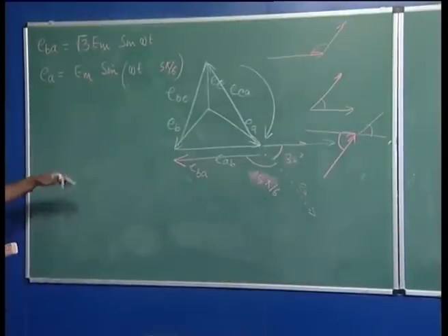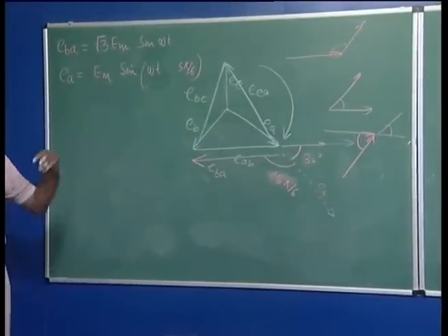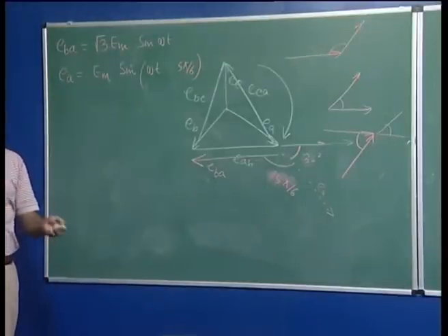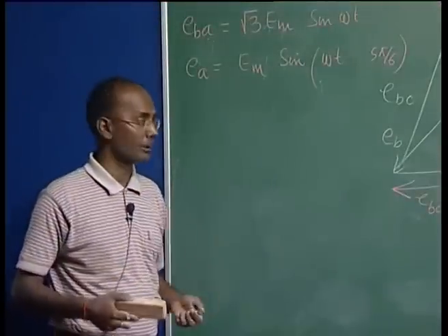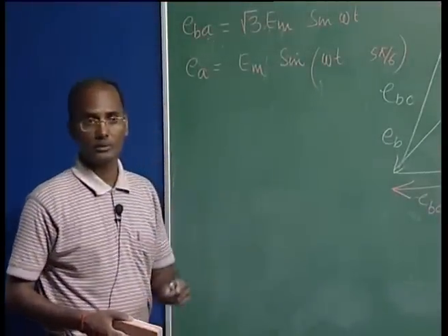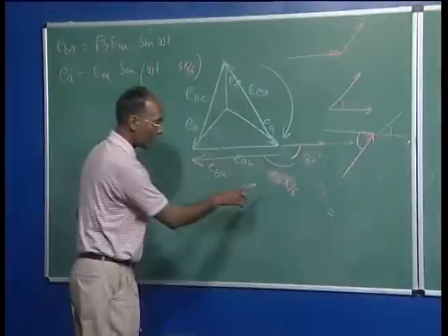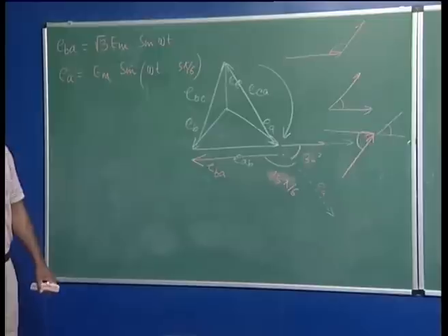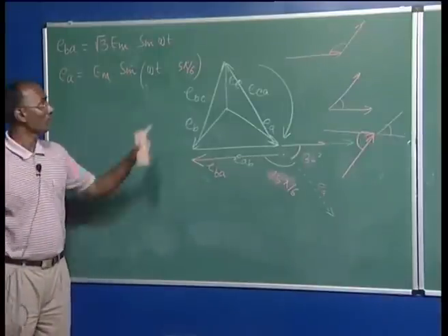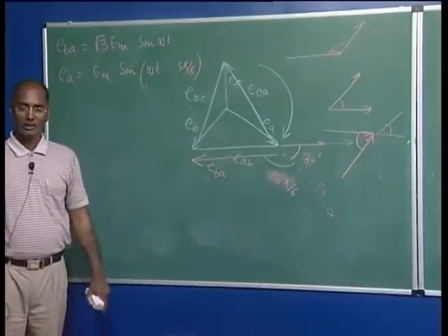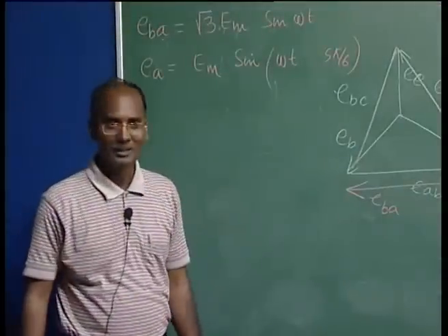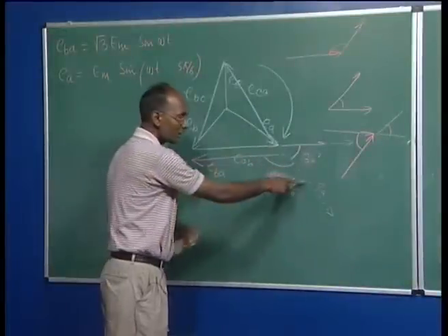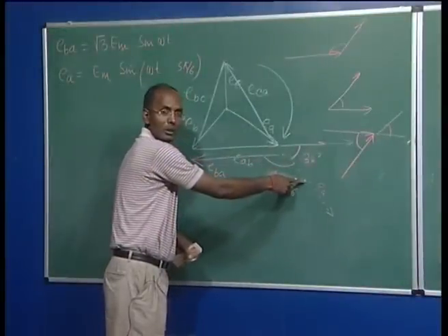So, it can be asked to write your DC output voltage in terms of phasor value, in terms of your line values, or even the line voltage in terms of the line or your phase voltage. So, this is very important to calculate. Now, we have derived that this angle is 150 degree, that is 5 pi upon 6. Now, whether it is leading or lagging, whether it is plus or minus. So, you just rotate here, it is just behind this. So, it will be plus.